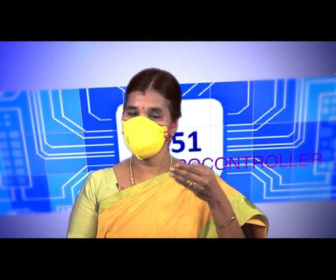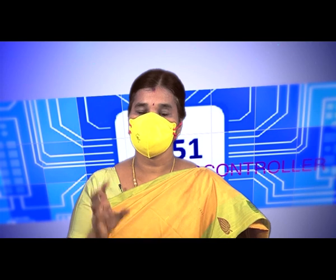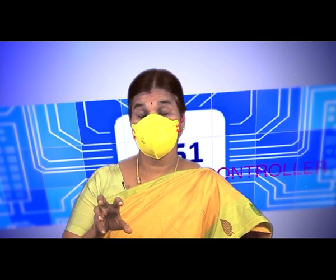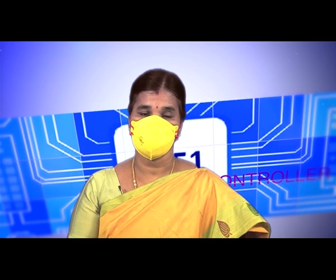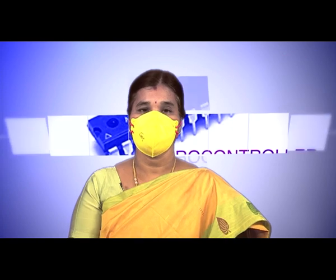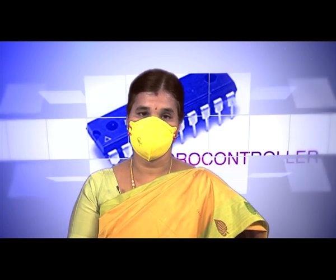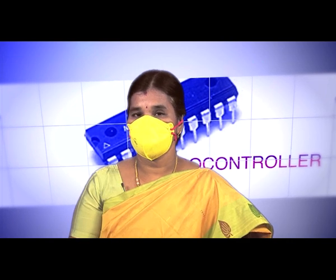The address lines are unidirectional, and they are a group of signals. The data line is bidirectional, which is used to read the data from the memory and also to write the data into the memory. Now, the data is available on the data line, whether it has to be read or written. So who will define the function or the direction of the data line? That will be defined by the control signals.